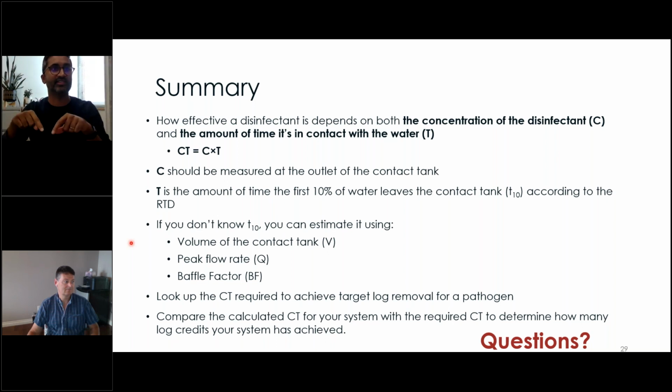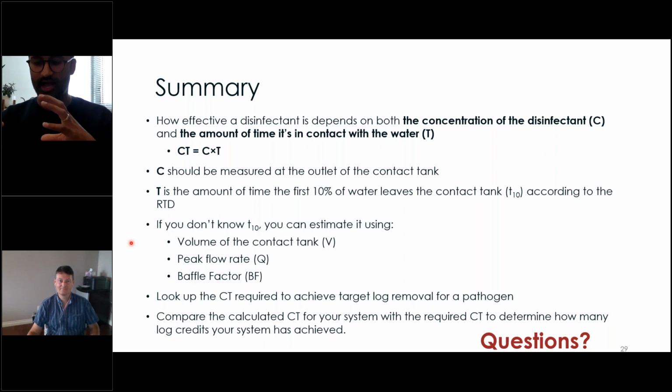That's a good question. What I would suggest is your boundary in which you're assessing the inlet versus the outlet should encompass that circulation. If you're recirculating, imagine you have a tank, and what I'm picturing you're describing is that at the outlet of your tank, you're recirculating back to the inlet of your tank. And then that's affecting your dose of chlorine.